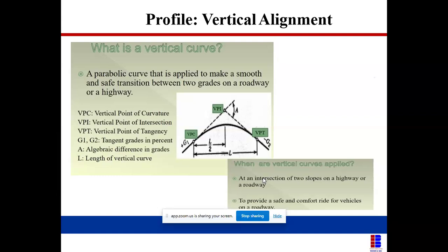So, if you are climbing a crest curve, you see that they will introduce what they call traffic management system drawing on our road as well. The broken lines on your road show you can overtake. But when you see a line that is thick and not broken, it shows you should not overtake. On those crest sides, those hilly areas, the lines are normally not broken lines. So the driver is supposed to be conscious that at that point you're not supposed to overtake a vehicle.